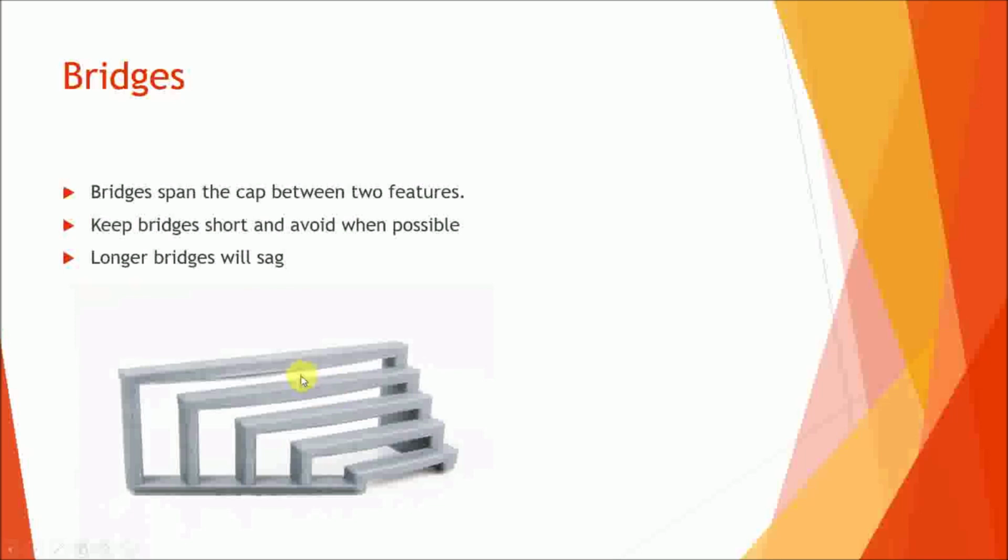Normally you need supports to print these larger bridges, but just so you're aware, you can bridge between two features as long as they're not too far apart. Longer bridges you want to stay away from, or just realize that they're going to need a substantial amount of support material to support that bridge.